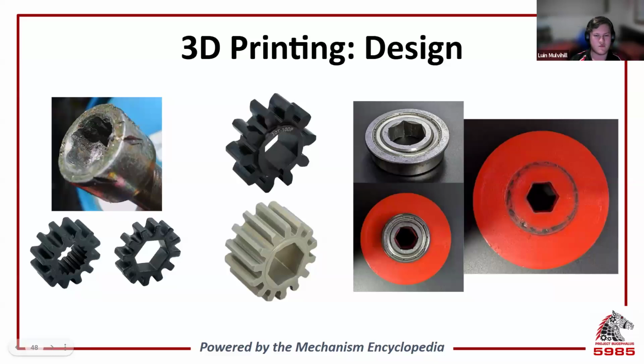The key to prevent parts from breaking is to spread the force over as much area as you can to reduce the stress experienced by the part. For pulleys, try using a 15mm wide belt where possible, and for gears, use a 10-tooth DP profile, as it makes each tooth larger, as well as trying to make your gear as wide as you can to spread the force out even more.